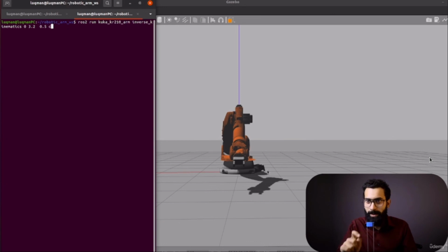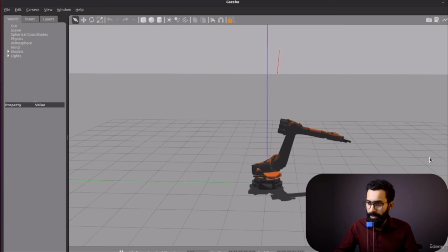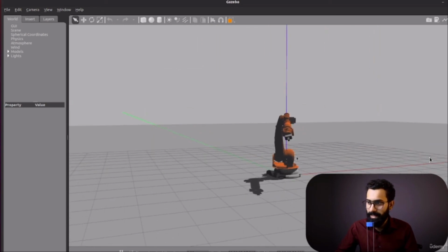Now I'm going to close the claw and increase the height in the z-axis, and make the robot move to negative x, negative y, 2.2 and negative 1.2. It is going to be somewhere in the middle. So let's take a look at the output. It should come to this point, in the middle of x and y, because both values are provided.